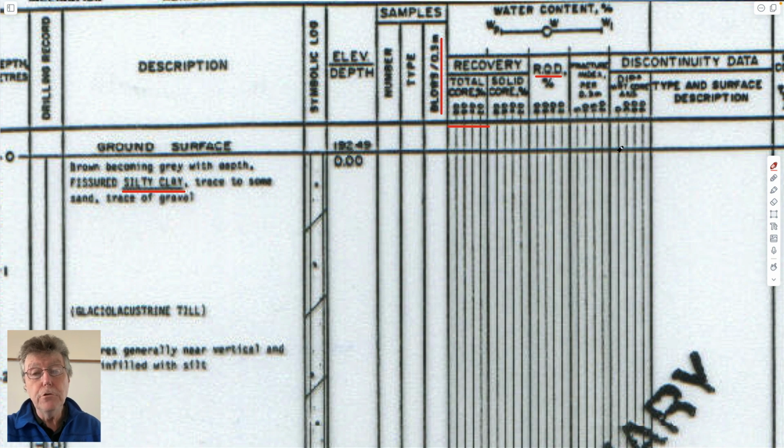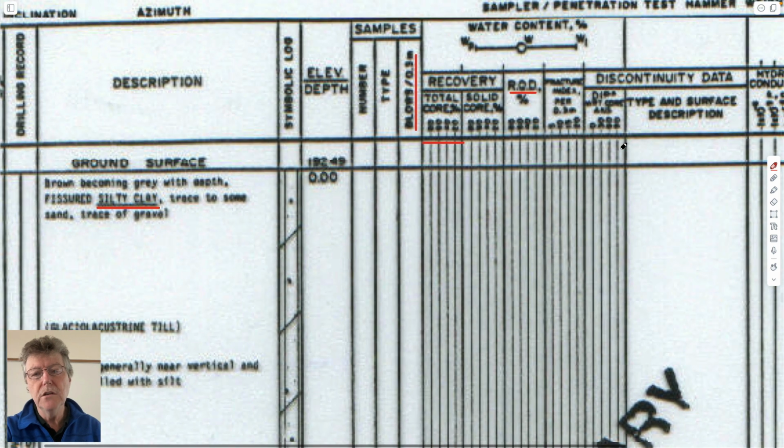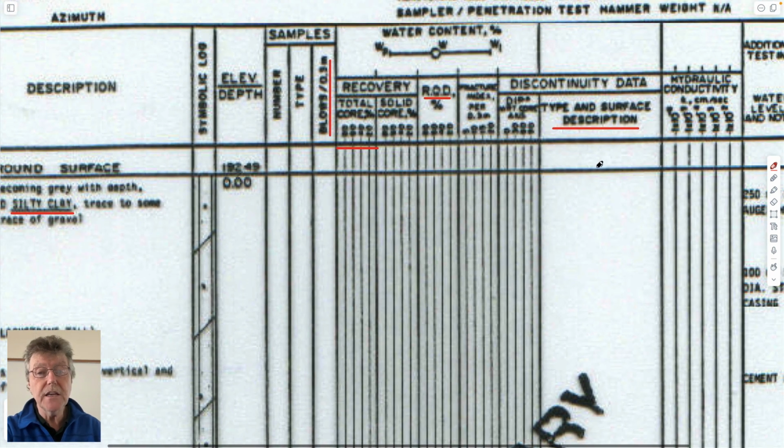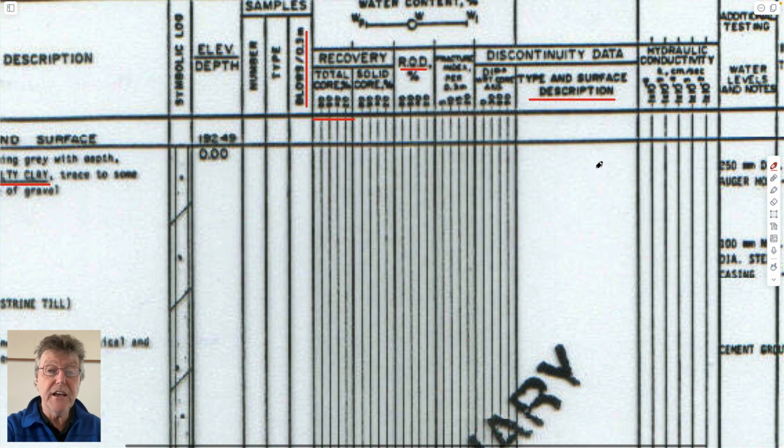And if you also sample rock core and bring it to the surface, you have the orientation of the fractures, which might be useful not so much for groundwater hydrology, but for designing things like rock slopes, where if you have steep fractures, they make the slope less stable. Whether you have surfaces on the fractures which might be iron stained, indicating that there's active water flow, or whether you have calcite deposits, or whether you have slickened sides as release surfaces.